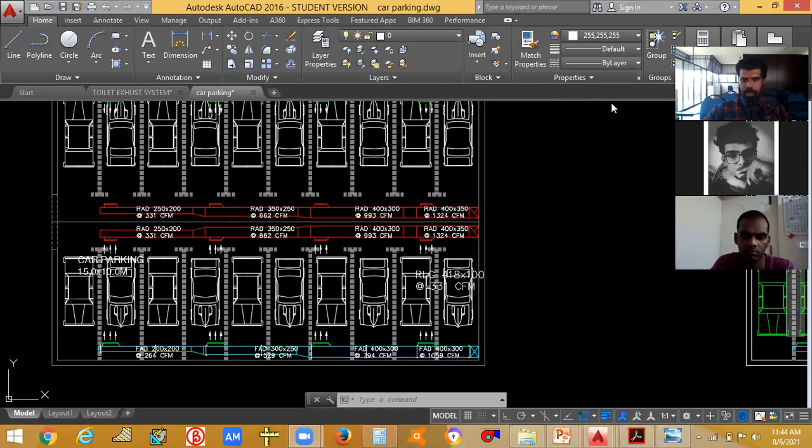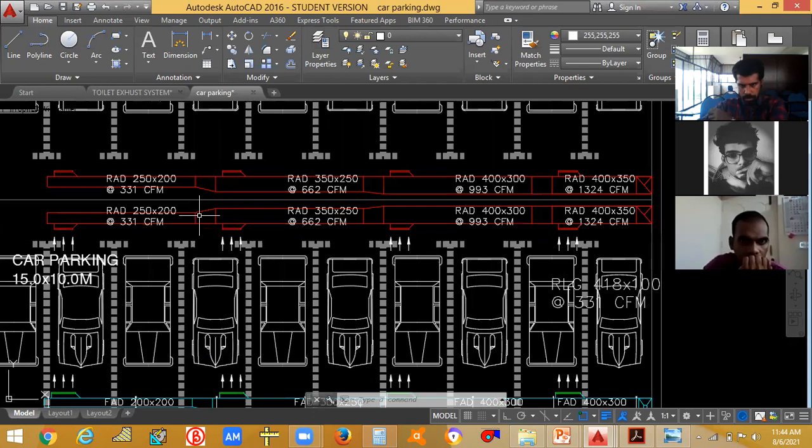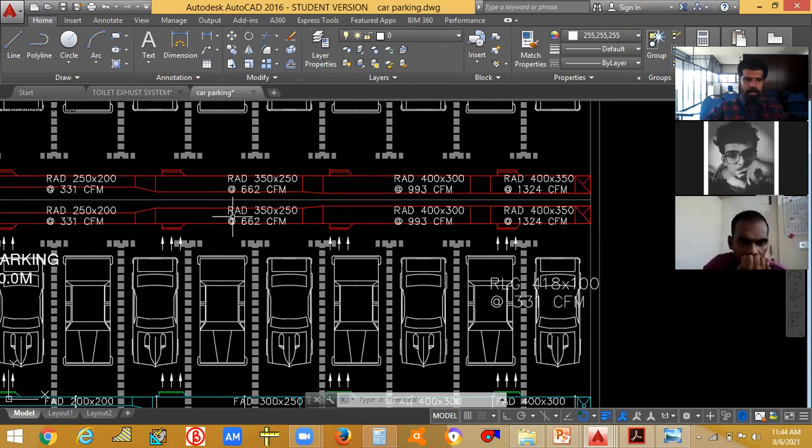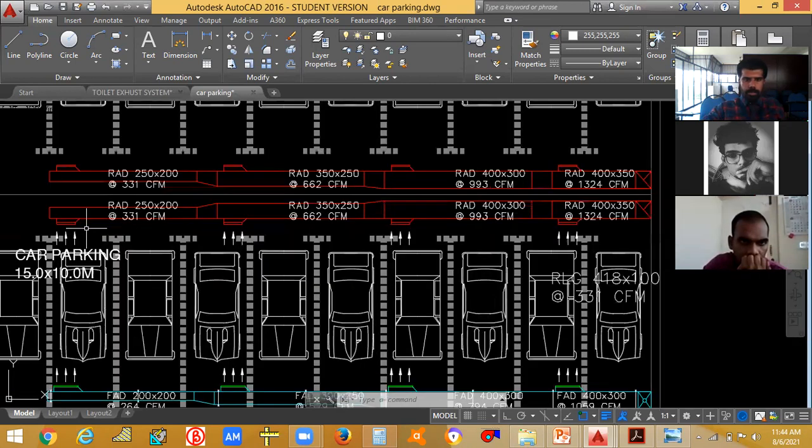I will explain this. What will be the friction loss while duct sizing? You can give 0.1. There will be a topic for duct designing, I will teach you that. Okay. I will explain this once, and then we can just start. So I have divided into 4 equal parts.